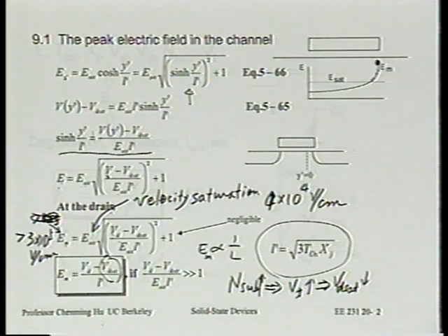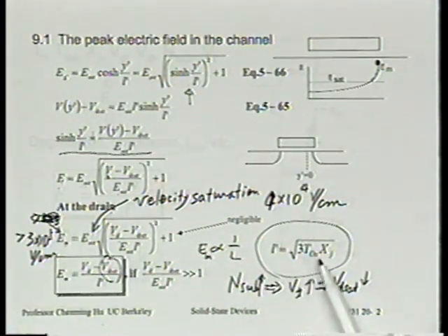Similarly, when they think that way, they will say, well, the electric field then must be a strong function of the doping concentration, because in a p-n junction, that's the only variable that affects electric field, really, other than the voltage. Turns out it's not. Doping concentration is a very weak factor here. And the problem with scaling of the device is because we scale these things.